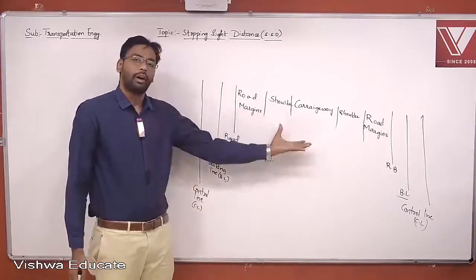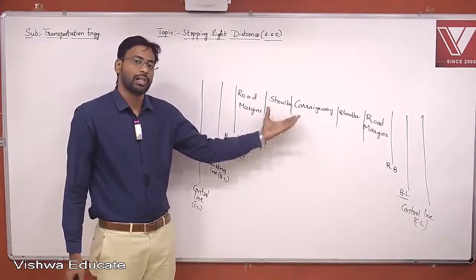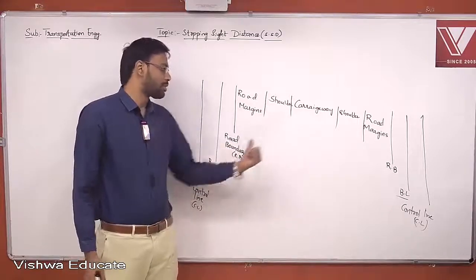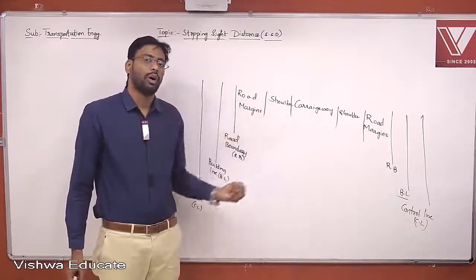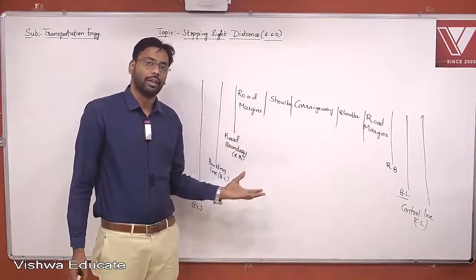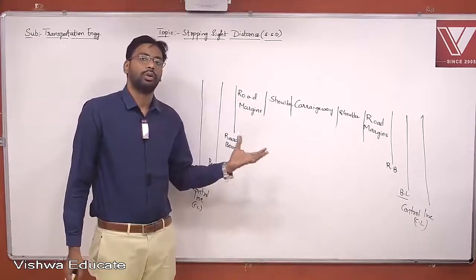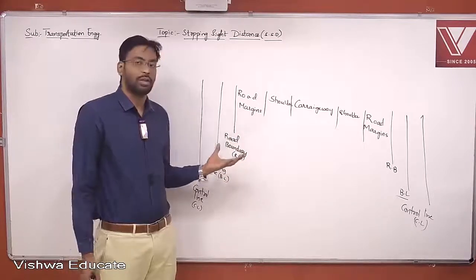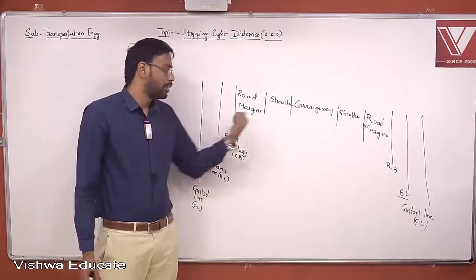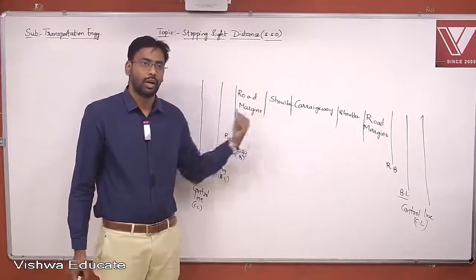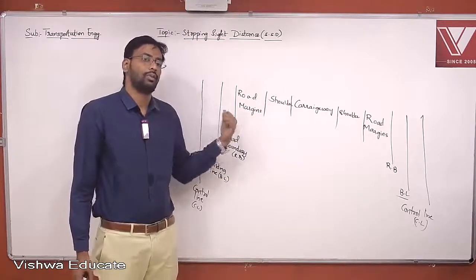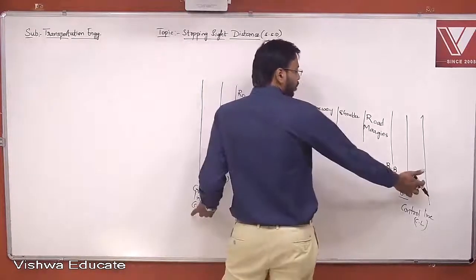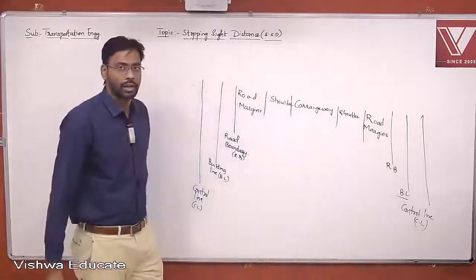The highway authority or the road authority has full right to do whatever they want up to these control lines. So if they want to further extend that particular road, they can go for the extension. They can do the demolition of the buildings also, even if they exist up to these control lines. Any modification, whatever the road authority wants to do, can be done up to these two lines. That is control lines, right?